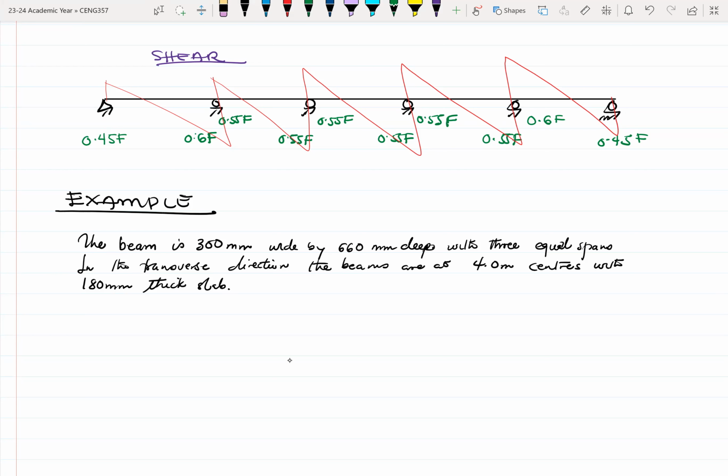As shown, I'll try and draw it. So our QK, which is a live load, is giving us 50 kilonewtons per meter, and the GK is given to us as 85 kilonewtons per meter. So this also includes the self weight, right? We'll look at some of these things. Include self weight once we start with the design, I mean the take home design. All right.